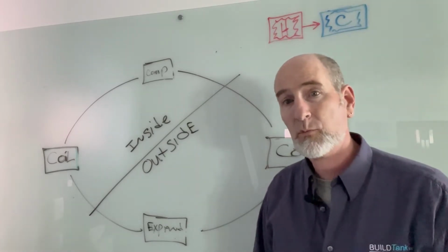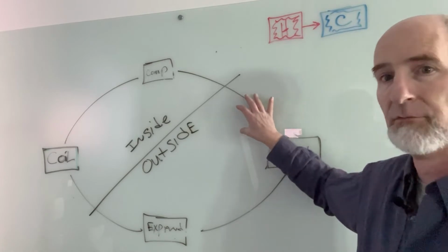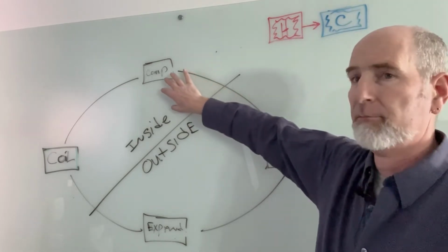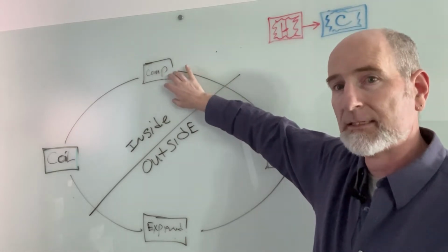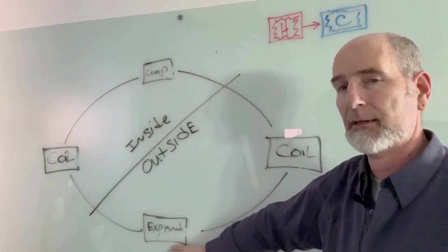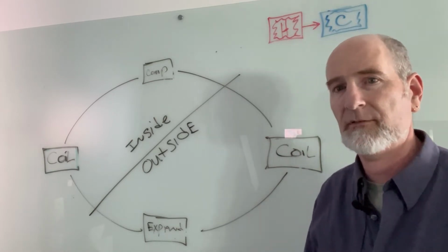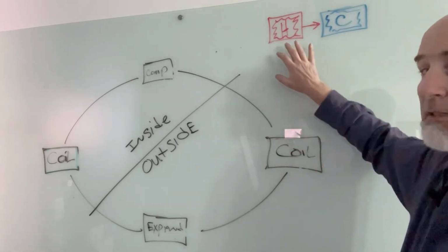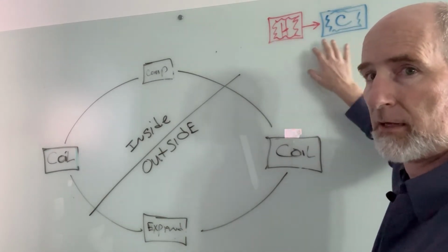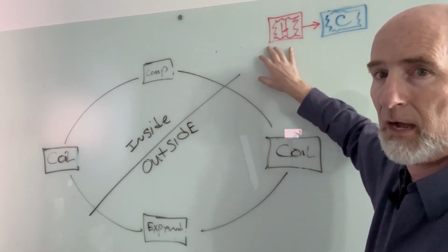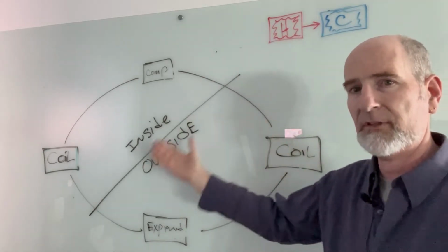So that's really the simple way that the system works. It's leveraging the magic of refrigerant, the magic of being able to compress it to increase its temperature, and let it expand to decrease its temperature, and then use the second law of thermodynamics, that energy moves from higher concentration to lower concentration. We can think of it from hot to cold there. And that's how we get the magic of this system working.